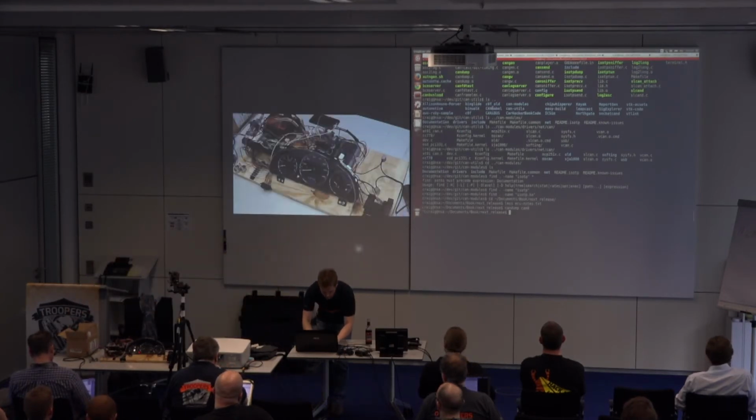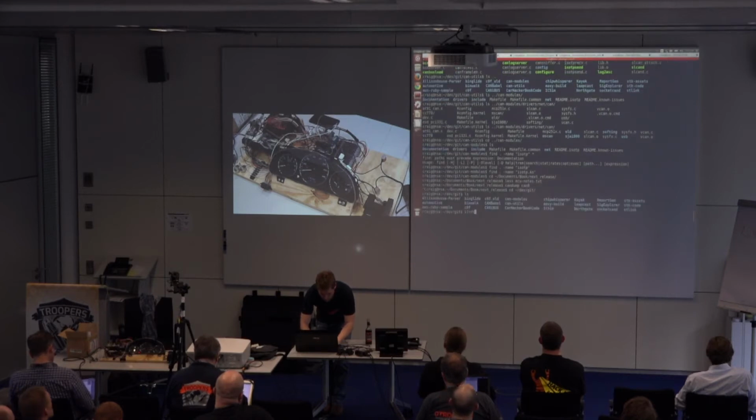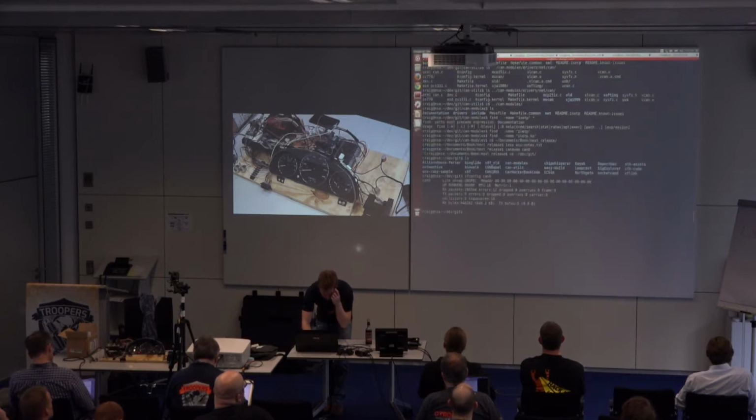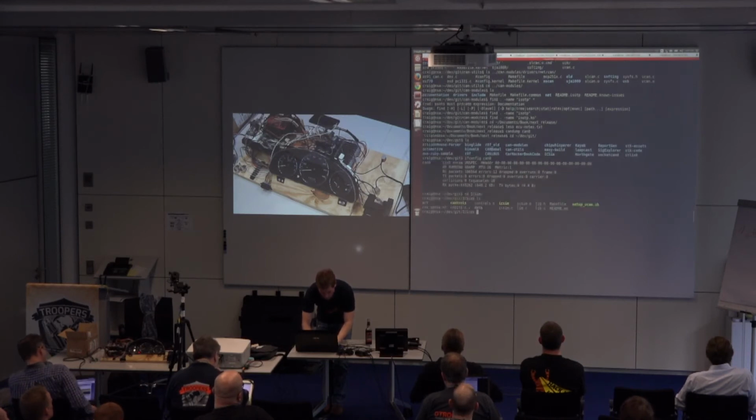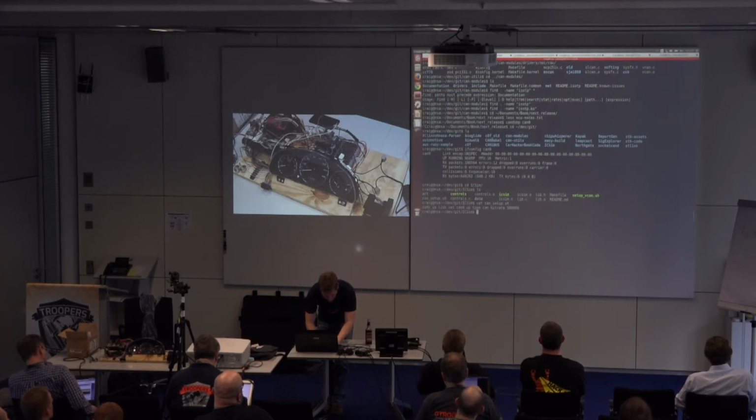I think I have to set the tool because I disconnected it. So it really just shows up in Linux as a CAN 0 device, and then you need to set the speed. I think I made a note on it real quick. So here's how you do it. You use the IP link, and then you set your bit rate.